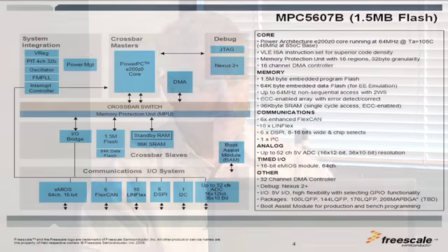It is disabled on power up, but the purpose is for operating systems for preventing illegal access. For example, a program mistakenly tries to write to the flash, and it's not a flash program, so you can prevent that. Or you maybe try to DMA to some peripherals that you're not supposed to. So it can be used to protect regions of memory from illegal access.